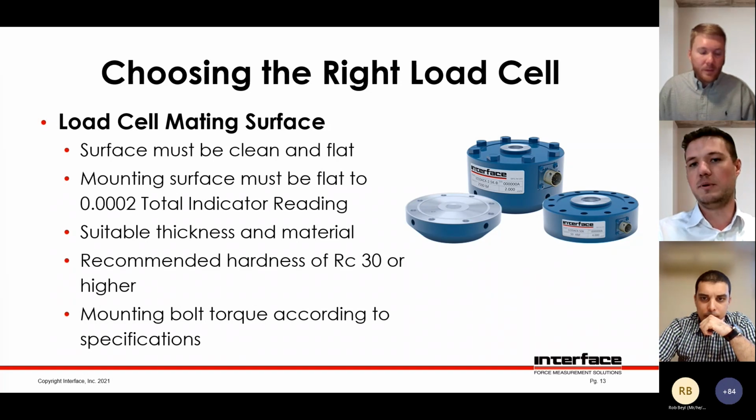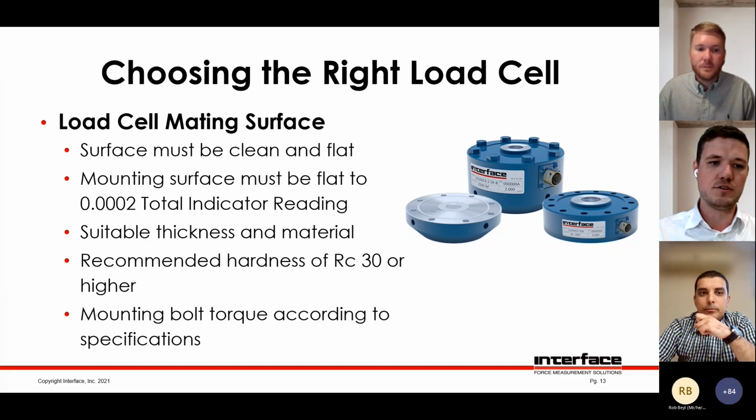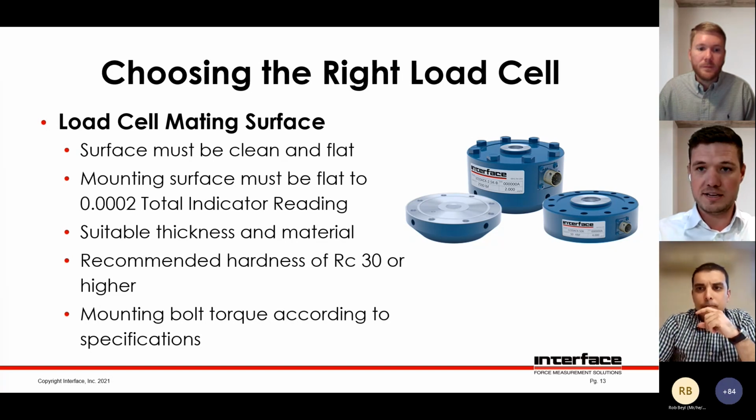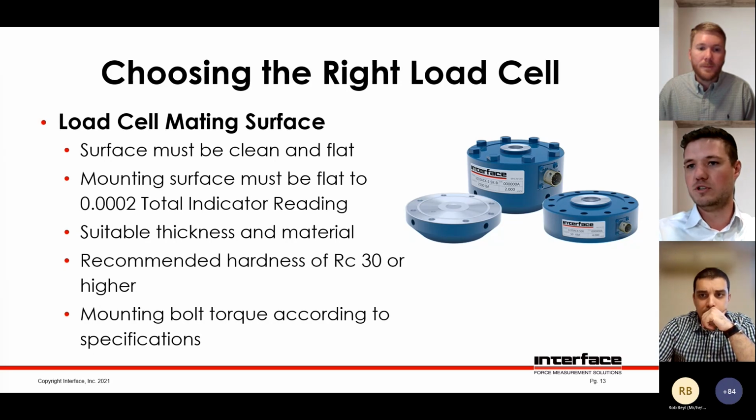It's also recommended that they're hard because obviously if they're deformed, that's taking deformation away from the flexure, which introduces error as well. It's good practice to apply the bolts on a base in a similar way that you would to lug nuts on a wheel on the car. You go in a star-shaped pattern and incrementally apply torque just so that it's evenly applied across the radial edge of the load cell. Thing I missed over there is that the base should be thick enough as well, because if it's too thin, it ends up bending or deforming, which then also introduces errors.